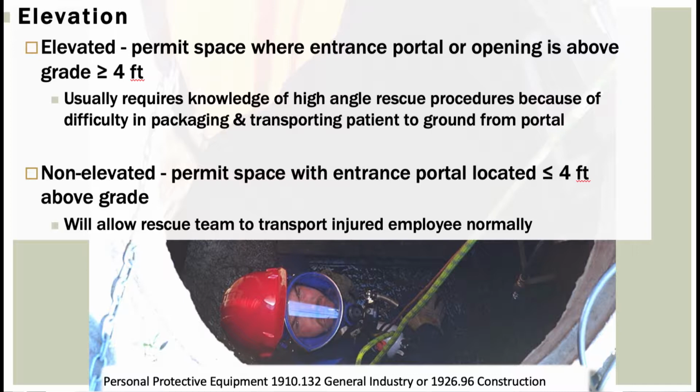So if you have an elevated entry portal, it's a permit required confined space when the entry portal or opening is 4 feet or more above grade. And this usually requires some knowledge of high angle rescue because of the difficulty of getting somebody out of a space or a portal that is at 4 feet. So it is at my head level or higher.